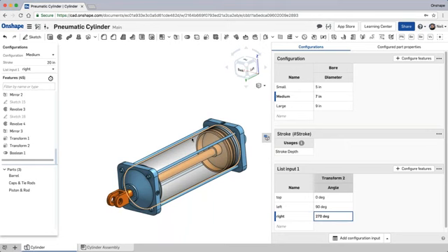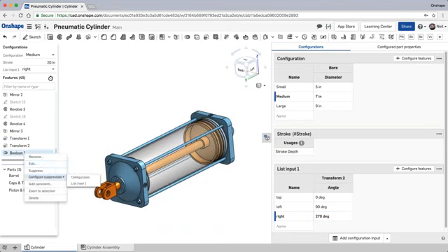And again, just to do something like that would be 30 plus rows or something in a regular design table. And again, you can suppress or unsuppress features, as Jay is asking there. So again, you can just take anything here and say configure suppression, and you can add the suppression to any of the tables that we've already created here. So that could be a part of it.